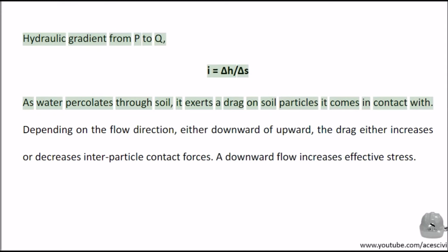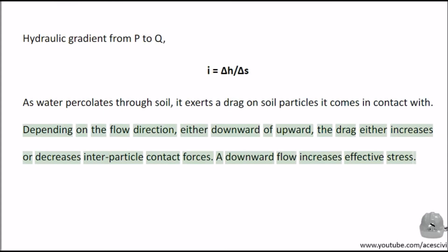As water percolates through soil, it exerts a drag on soil particles it comes in contact with. Depending on the flow direction, either downward or upward, the drag either increases or decreases interparticle contact forces. A downward flow increases effective stress.